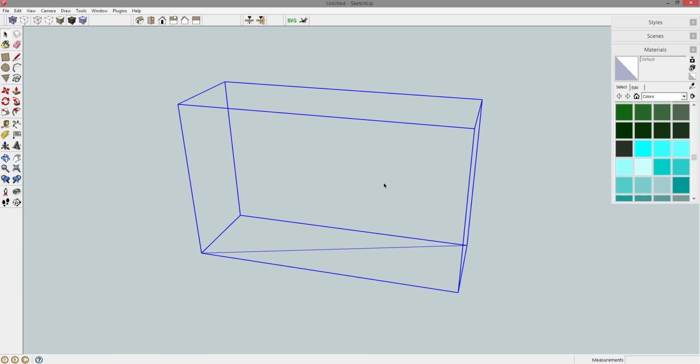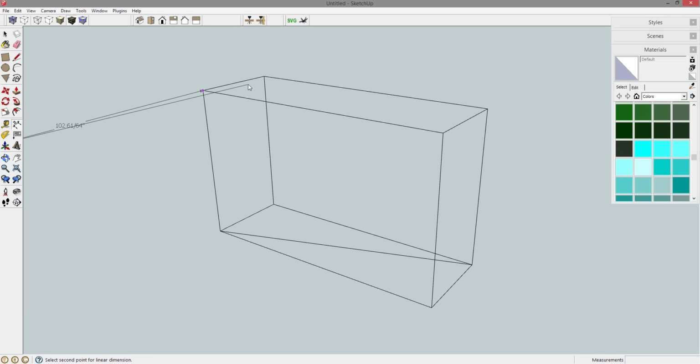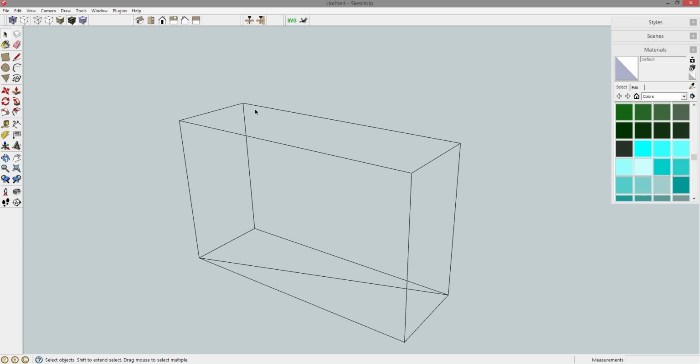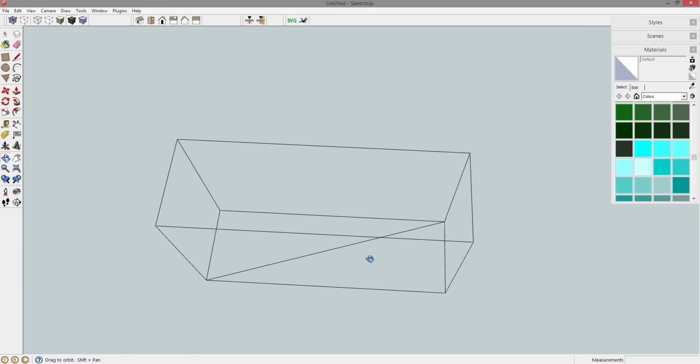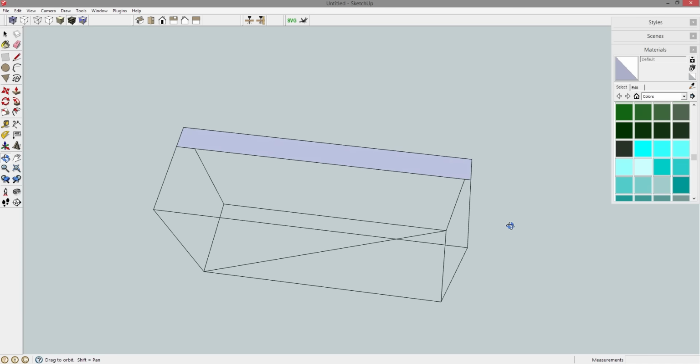Let's draw the top first, and the top, like I said, is going to be 16 inches front to back. That's evenly divided by 4. So there will be 4 planks in this particular glued panel, each one 4 inches in width. So from the top, let's press R for rectangle. And just constraining to this opposite edge over here, the dimensions say my second is the shorter of the two, so let's press comma 4, enter to modify the second dimension only.